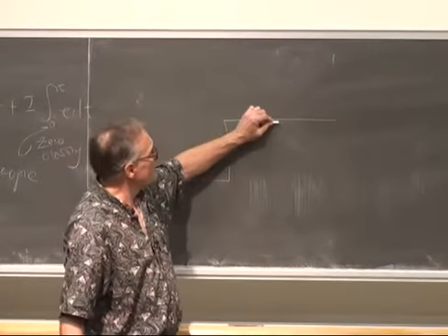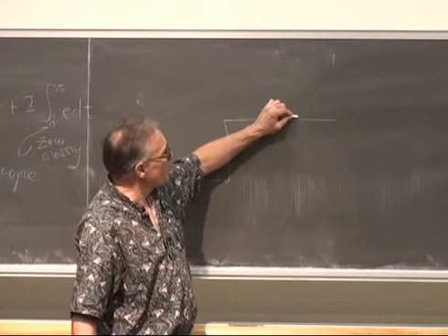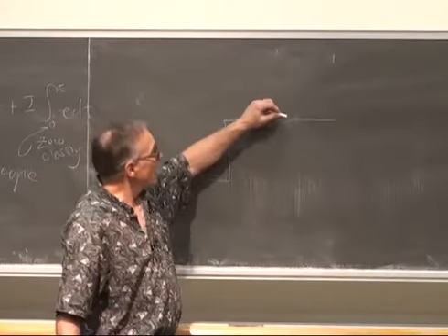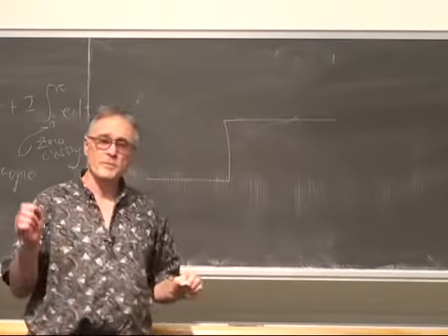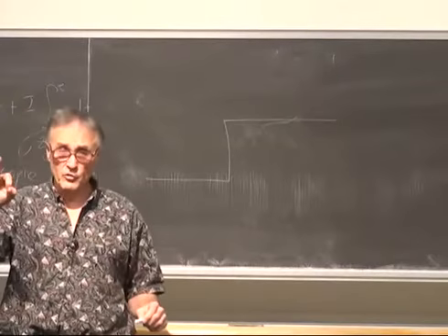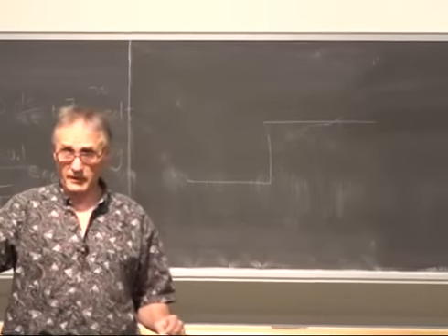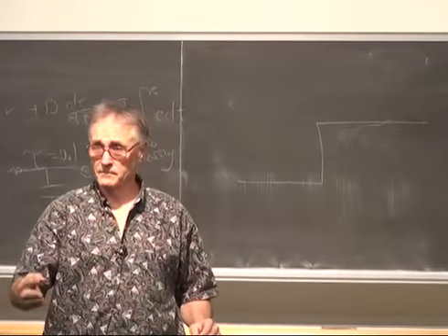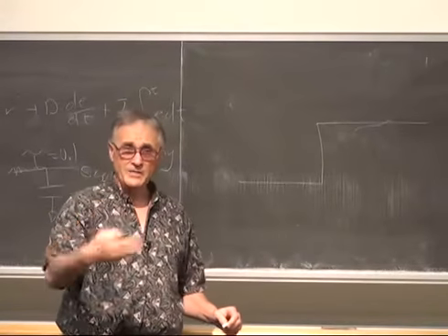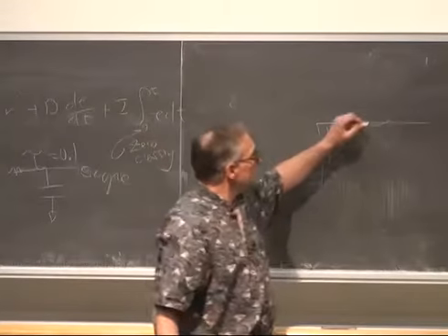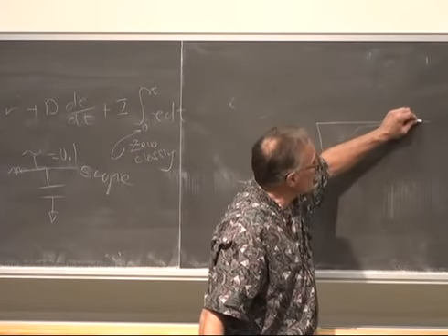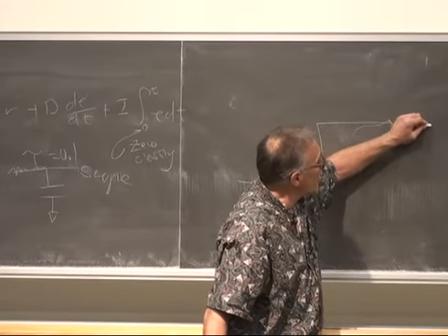The integral term starts to accumulate, comes over the value of the desired speed. As soon as it crosses over the desired speed, the only thing you can do with this control system that we're building is turn it off. That'll slow it down as fast as anything you can do. So you turn it off, it exponentially decays back down, builds up again, turn it off.